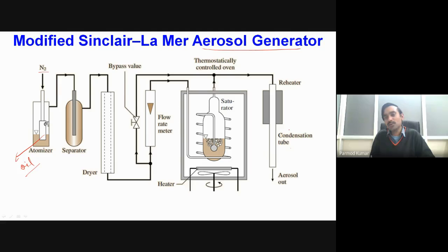In this device, what we are doing initially, while our particles come out of this heated chamber, is having particles in the form of vapor, which is saturated vapor. While this saturated vapor enters our flow field, it will liquefy and convert into liquid droplets, which will act as our tracer particles.